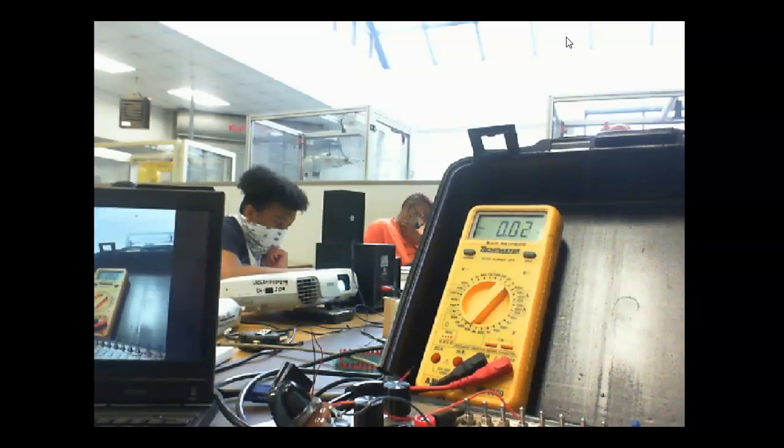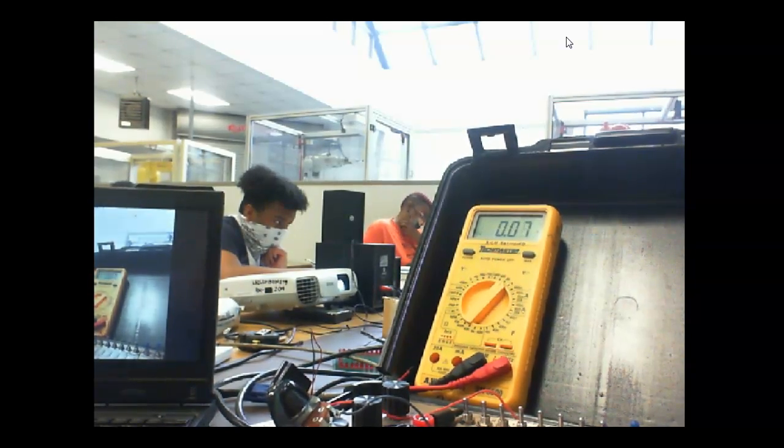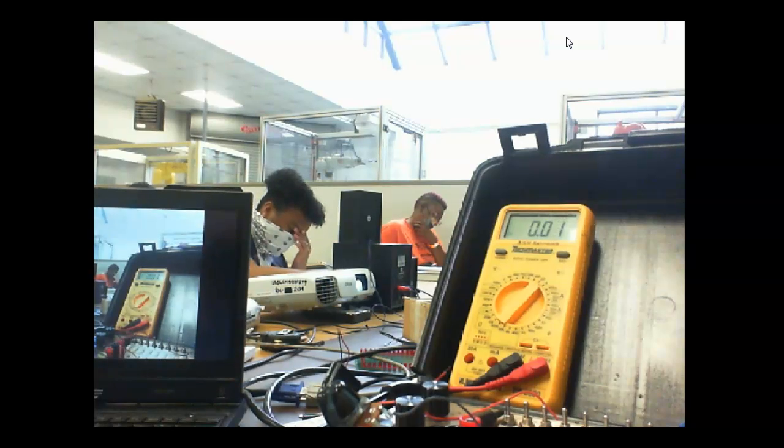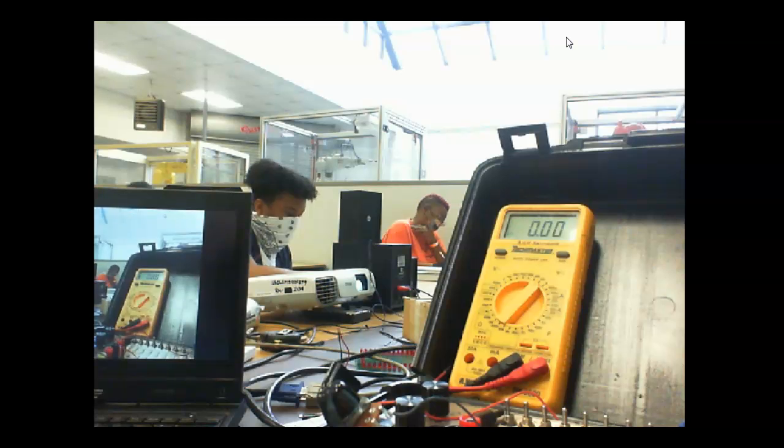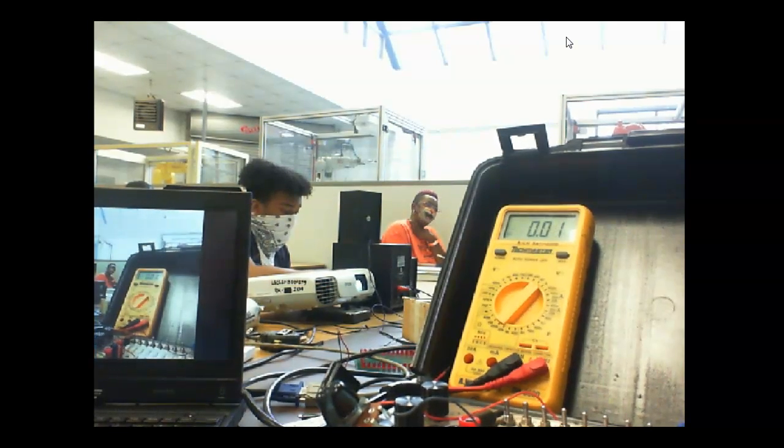I'm trying to see what the output signal would be. My emitter voltage has gone up to, instead of being 1 point something, 2.6 volts. My collector voltage has dropped down to 2.75, so the transistor's going into saturation, right? Understand that? I was trying to look at the output signal to see what it would look like, but it's going to be all distorted.